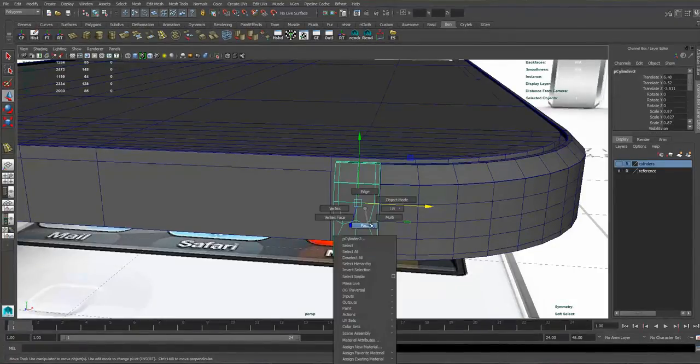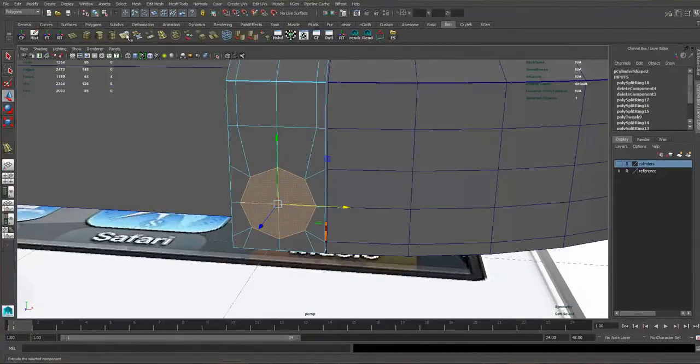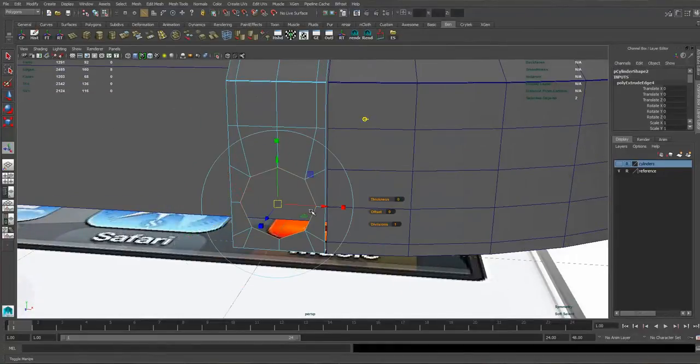I actually need to create the hole. So I'm going to select these 4 faces here. I'm going to hit delete, and then I'll select the edges on the inside by double clicking on these edges here. Hit extrude, snap to grid button before I pull anything out, and then get these. So click on a cube on the top and then click on a cube in the center to resize down.